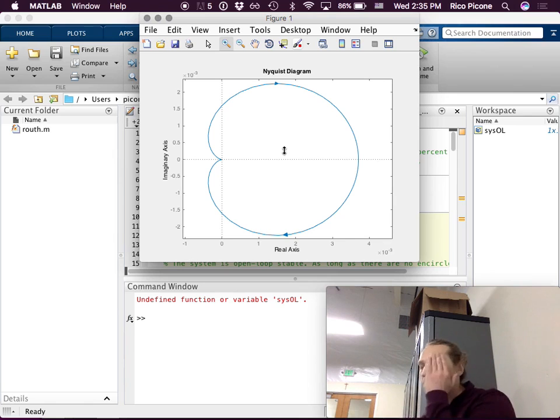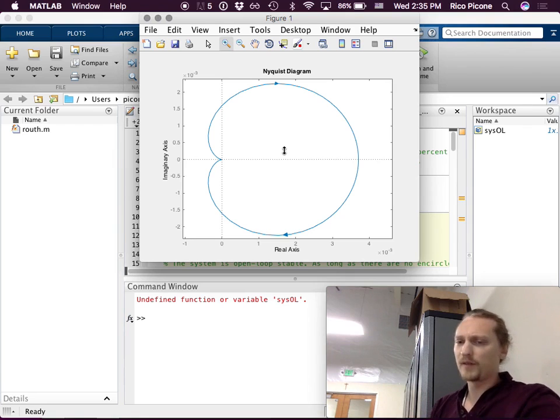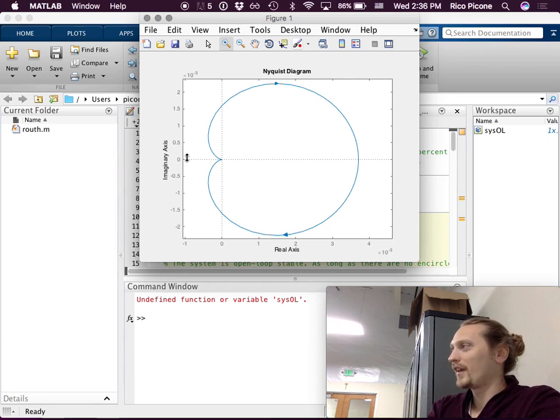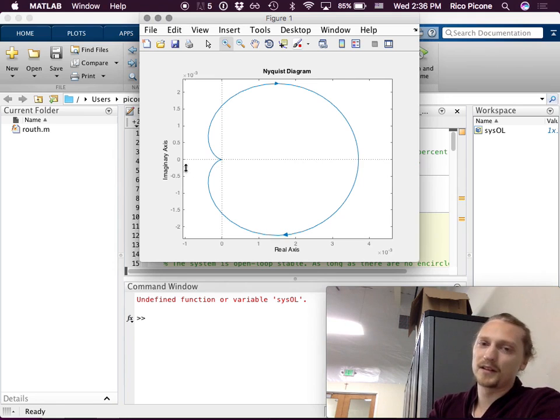So we're going to be using the phase margin, but since we're still getting used to Nyquist diagrams, let's talk about phase margin and gain margin here. Do you guys remember the definitions in terms of the Nyquist plot? The magnitude at which it crosses that arc and then the angle that is. Yeah, so the gain margin depends on the distance between the real axis crossing, hopefully single real axis crossing, and -1. So the negative real axis crossing and -1, not the positive real axis.